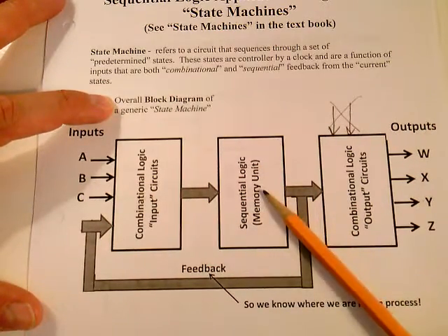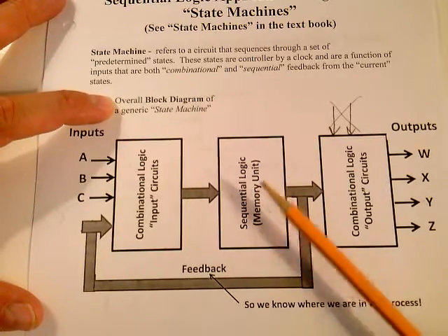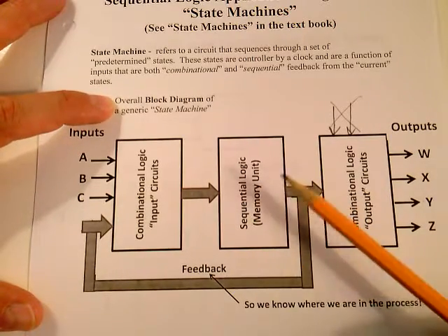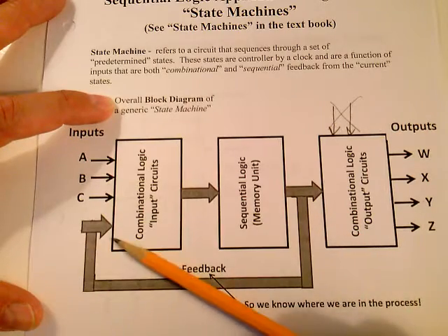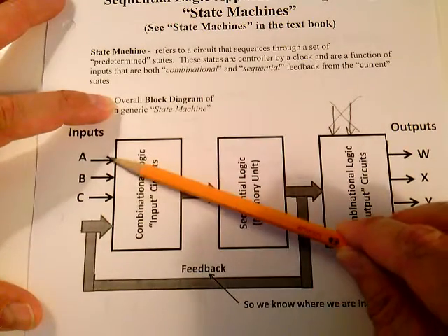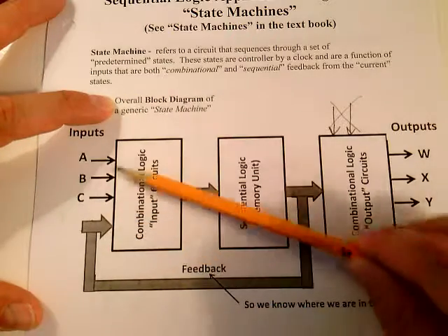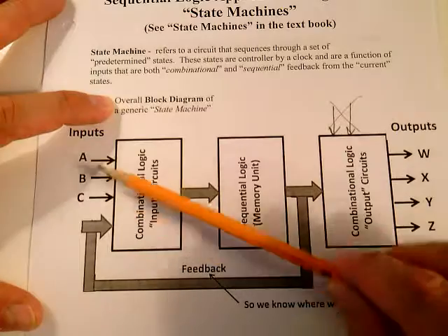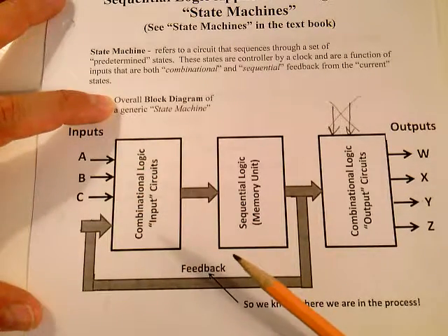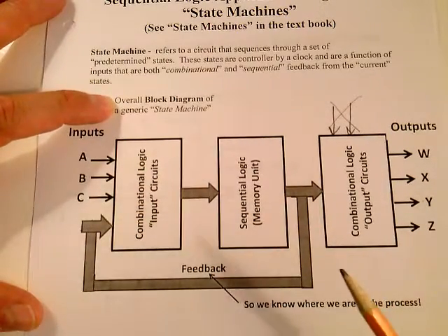You might have one flip-flop, two flip-flops, three flip-flops, and so on, but for every flip-flop you could have a line being fed back as an input. And the total number of inputs you have, your external inputs plus your feedback inputs, tell you what variable map you'll use. I mentioned that to you.